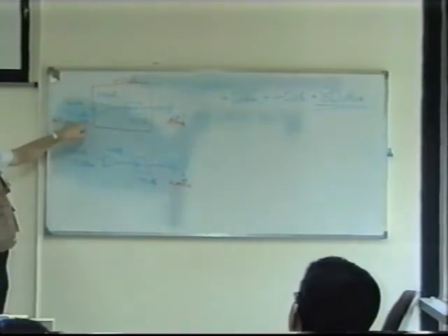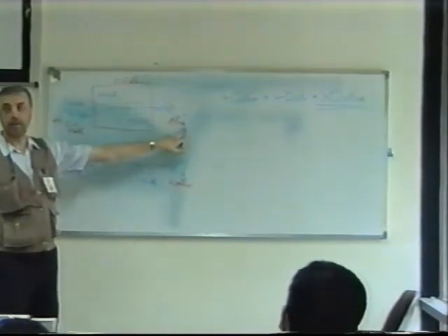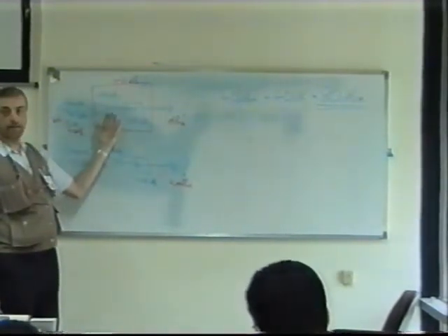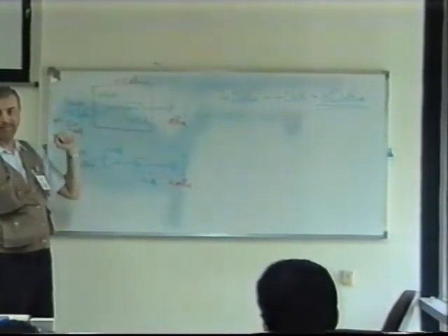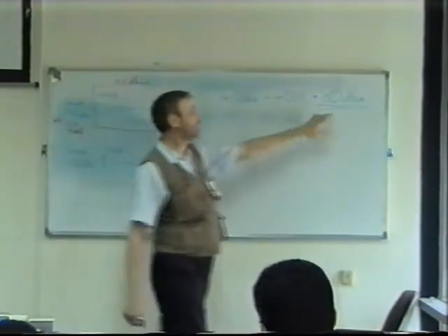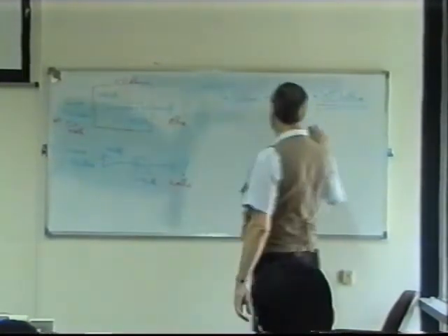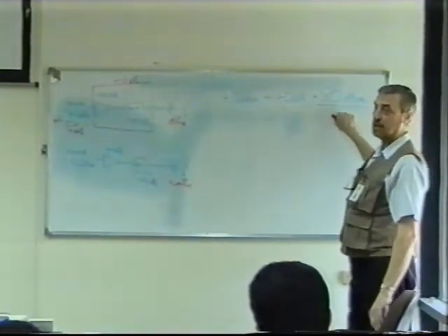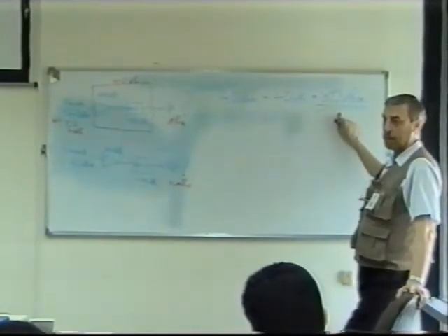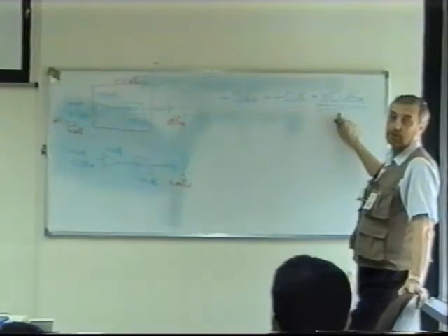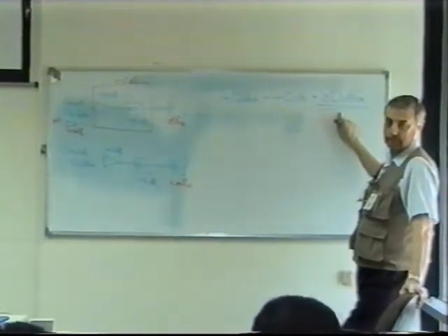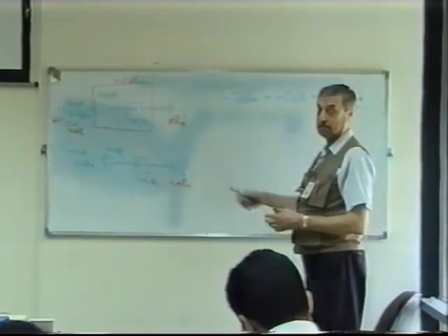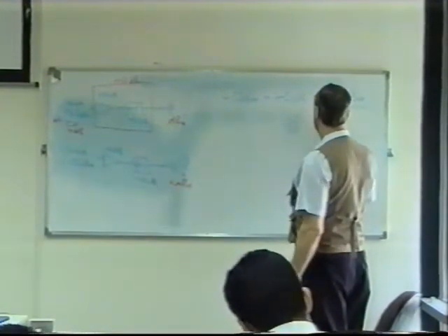So if you've got an input power in dBm and you're asked for an output power in dBm, then of course just do your adding and subtracting, right? And then you end up with 80 dBm. Now if you wanted to, you can change this to watts. But it's not necessary. If it's watts, it's 10 to the power 8 milliwatts, which is 100 kilowatts. Right, what's 80 dBm? Well, in fact, we're going to do that here. That's 10 to the power 8, isn't it?